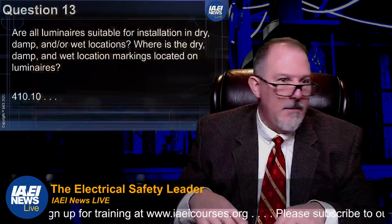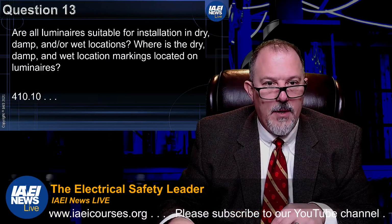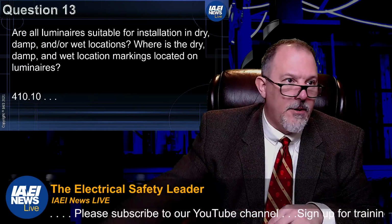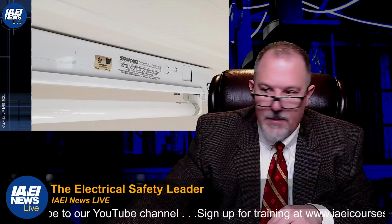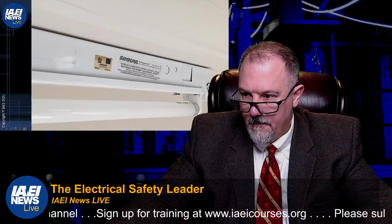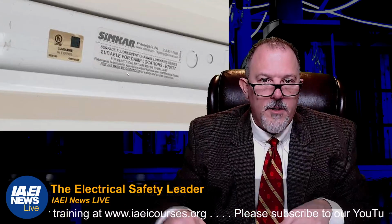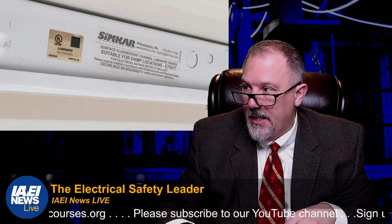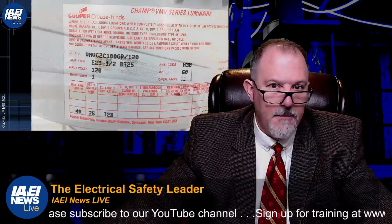All right, so let's take a look at the next one. Are all luminaires suitable for installation in dry, damp, and or wet locations? Where is the dry, damp, and wet location markings located on a luminaire? Well, that's what it says right here. Surface fluorescent channel luminaire, Series suitable for damp locations. So it specifically says damp locations.